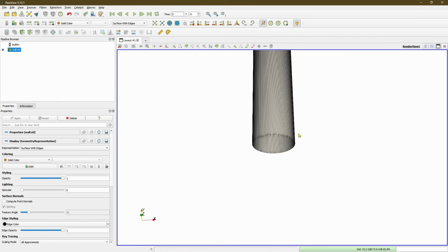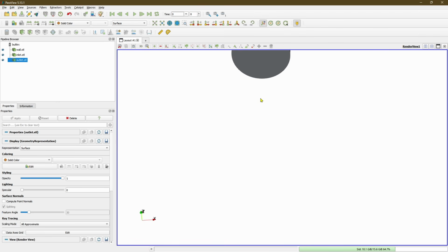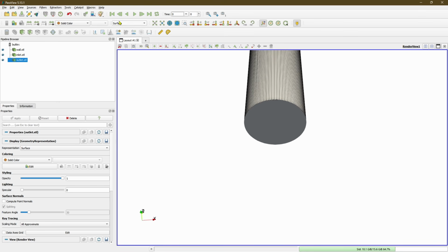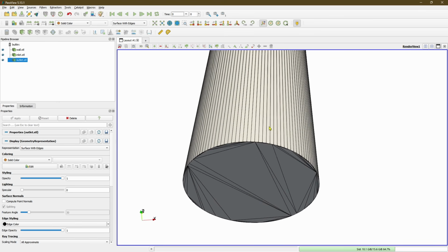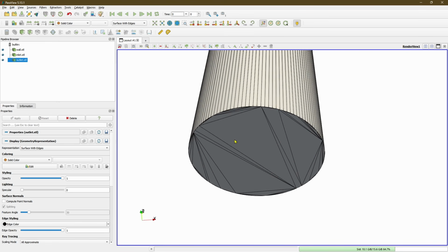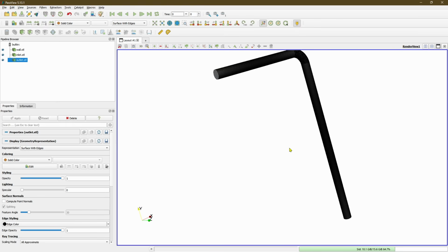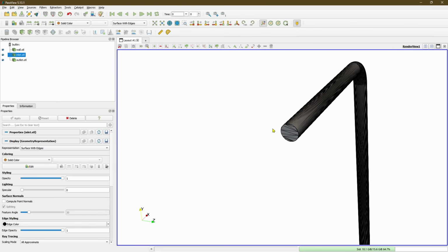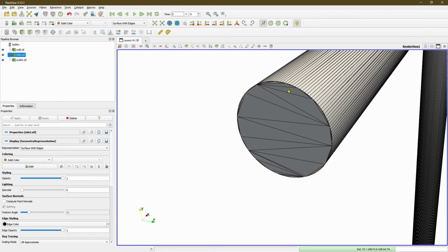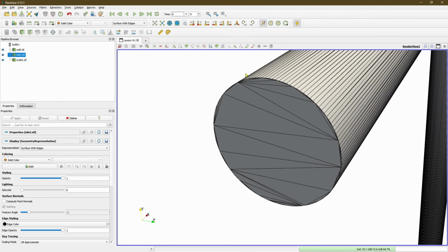The same thing we will do for our inlet and outlet. So we have exported the inlet as well as the outlet. If you want to take a look at this, this is my outlet. Not the best, but we essentially need the outlet shape, not the inside triangles here. And similarly, we have our inlet. Same type of triangles, but serviceable, we will just work with it. So that's how we create the geometry. Now let's move to creating the mesh.